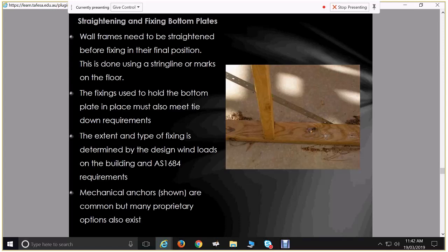Your blue tips are a really coarse threaded bolt. So you can drill a hole smaller than the shape of the blue tip and then just drive it in with a rotary hammer, or not rotary hammer drill, but a driver. Impact drill. Yeah, impact drill. And that coarse thread will cut the thread into the concrete and lock itself in there.